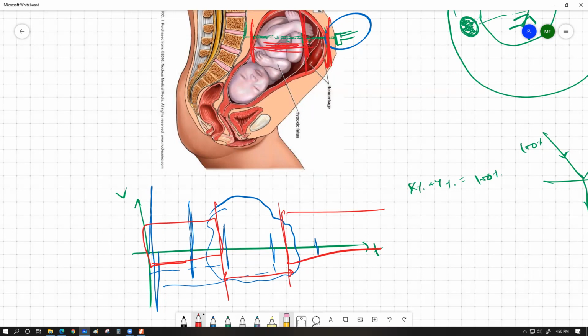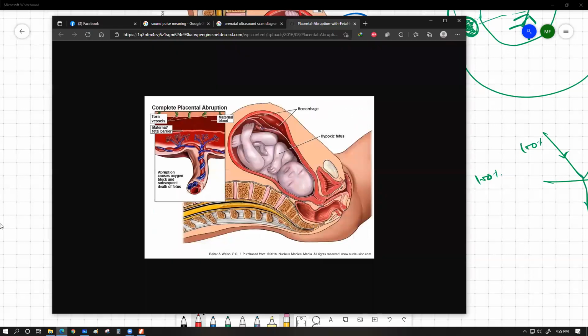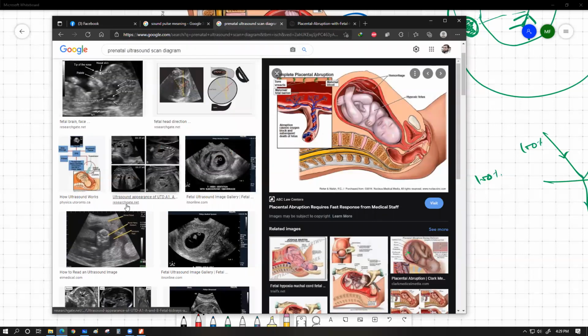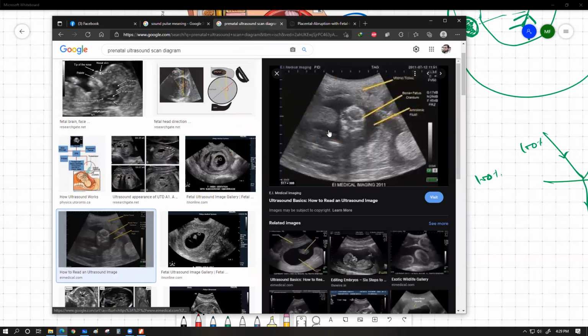So the probe is going to give us the reflection value for all of them, but the software is going to discard all the other reflections other than a very specific time amount, and those specific reflections are going to be displayed on a two-dimensional screen as white pixels, and non-visible locations will be represented by dark pixels, which ultimately give us this black and white figure like this.